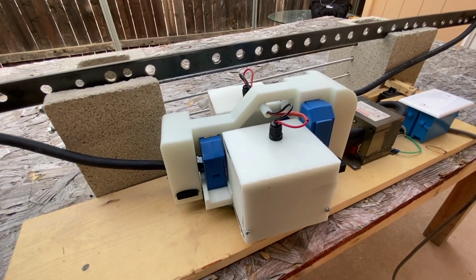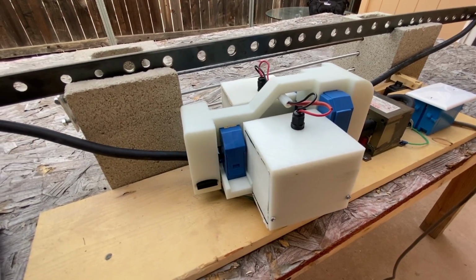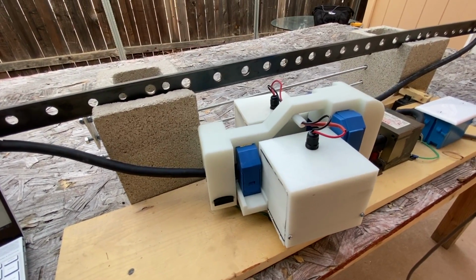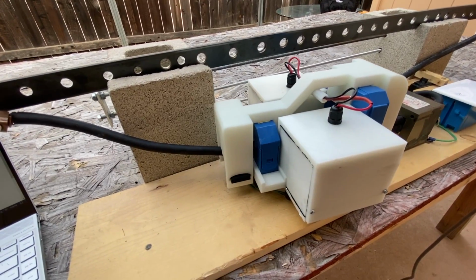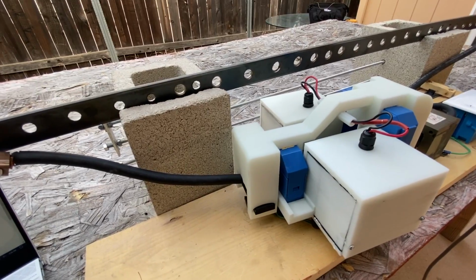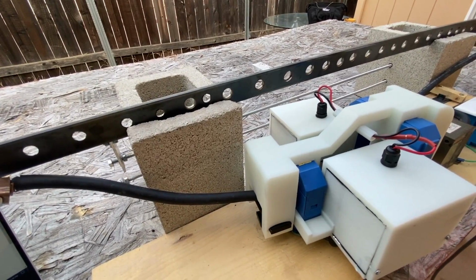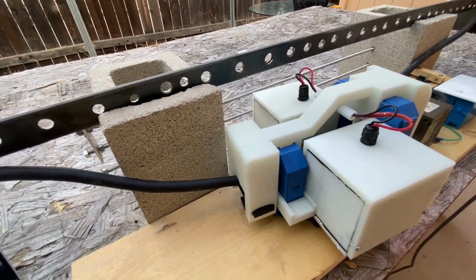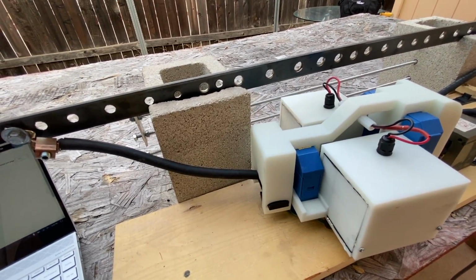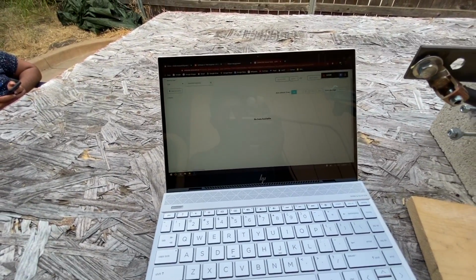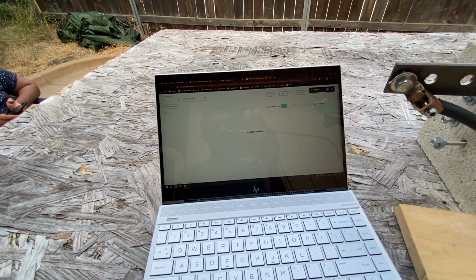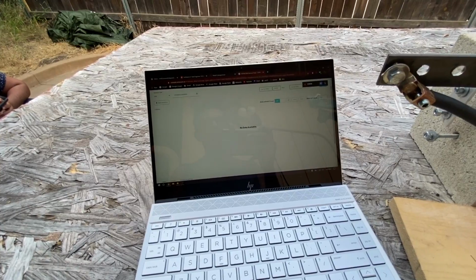Now I'll discuss the data collection software that this device uses to detect faults and other disturbances. The PCB, which contains the sensors, is connected to a SIM module, which is driven by the microcontroller to send data via a TCP connection to a server here. This server is provided by Soracom and allows us to process data.